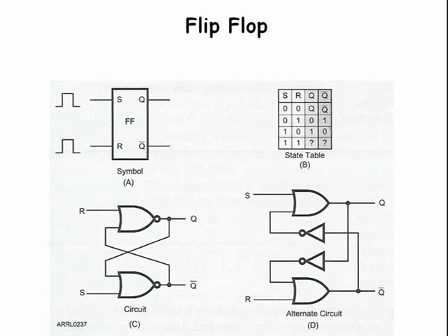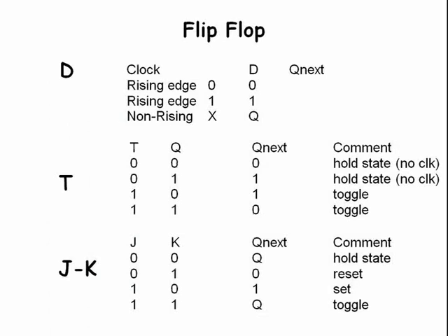There are several types of flip-flops, including synchronous and asynchronous units. Synchronous flip-flops change output states only during prescribed times determined by the clock input. Asynchronous flip-flops can change output states whenever the input states change.